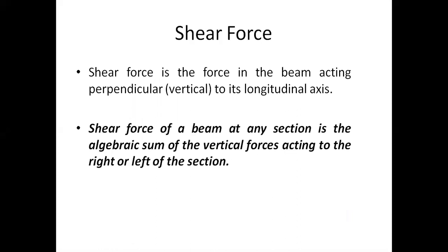Here is the definition: the shear force of a beam at any section is the algebraic sum of the vertical forces acting to the right or left of the section. That's what we have done in the previous example. On the left side we have 500 newtons, which is the resultant of one force. On the right hand side we have two forces, and the resultant force is also 500.